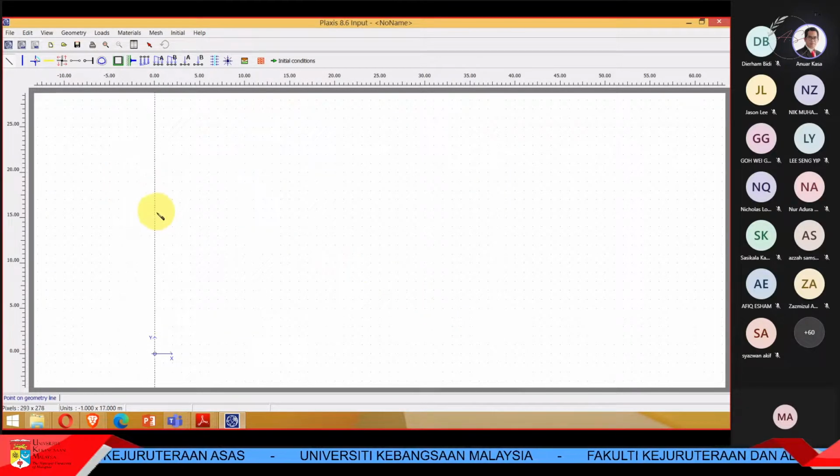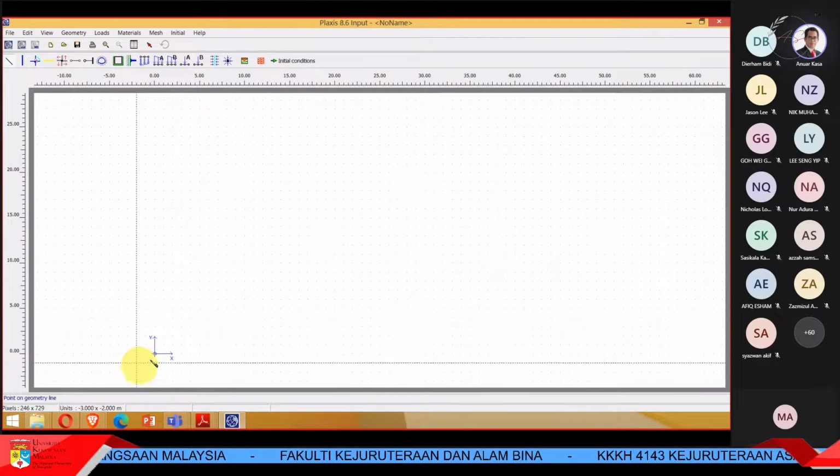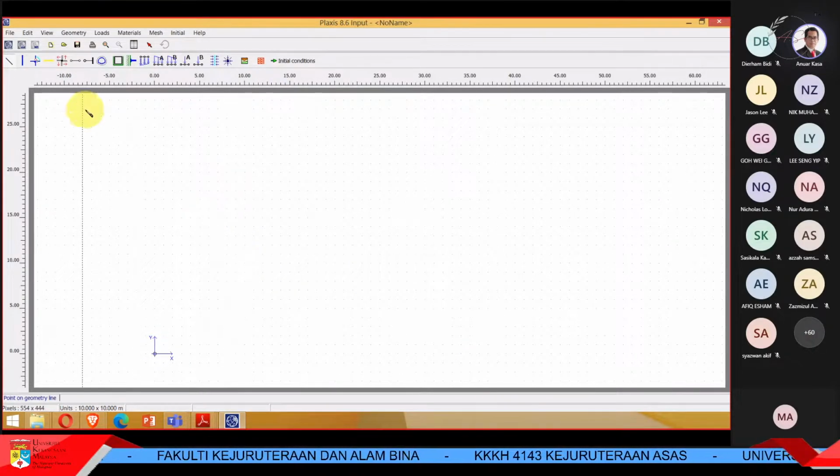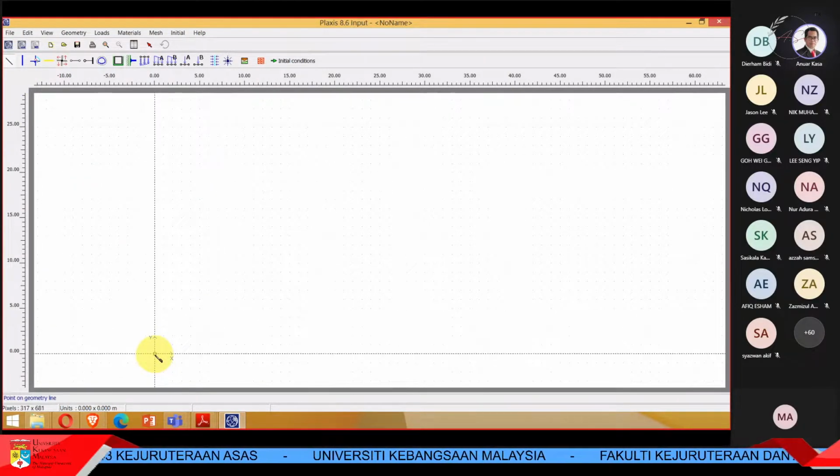Okay. So actually, designing using Plaxis starts from the left to the right. First of all, we need to create a geometry. Okay, I just create the geometry. First it automatically has the line tool, so click on the line here. Let's say we have a geometry something like this.